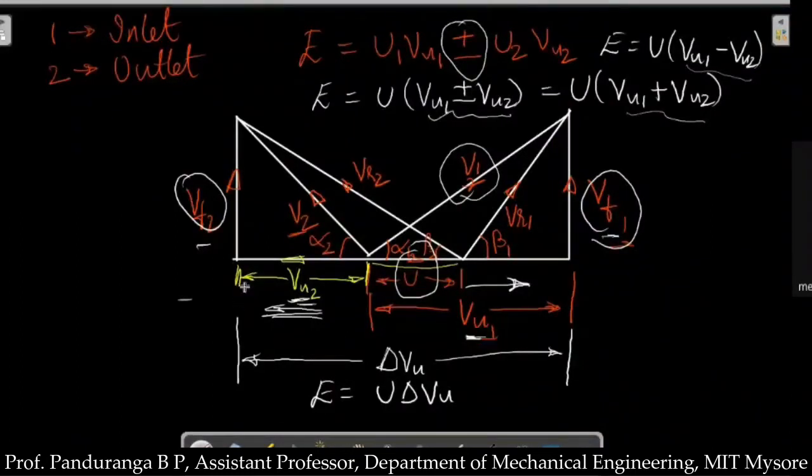While solving problems, you can use two different methods in solving turbomachine problems. One is the analytical method, and the other one is graphical. In the analytical method, we use the trigonometric relations for beta 1, maybe cos beta 1, sin beta 1, tan beta 1, the Pythagoras theorem, because we're dealing with right angle triangles here, and then the cosine rule.